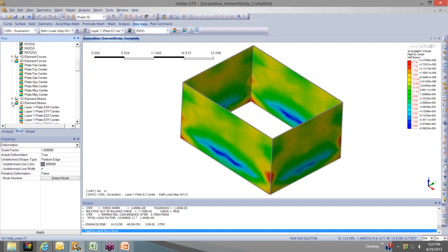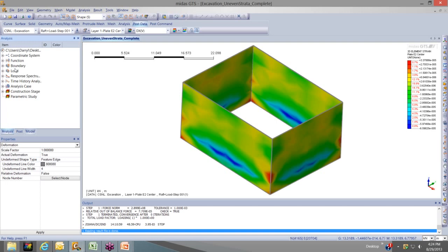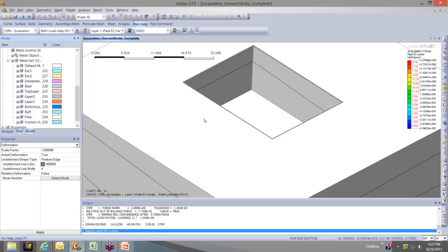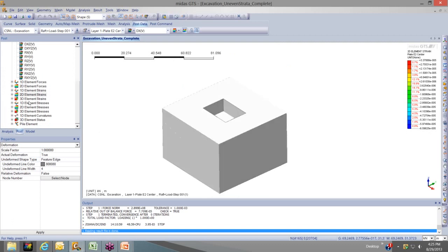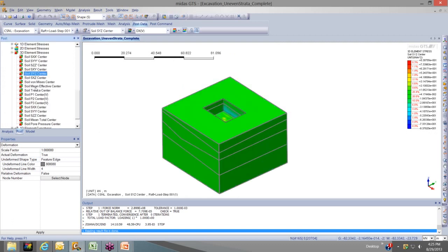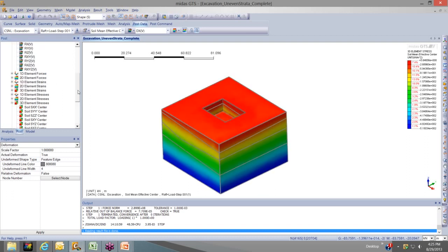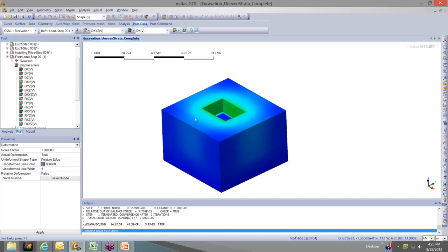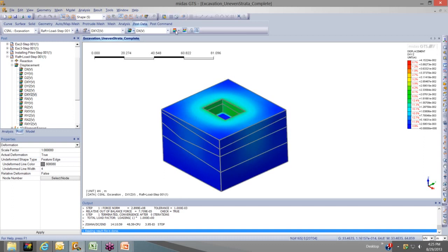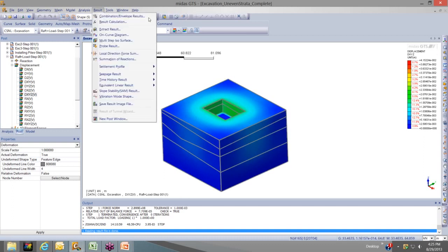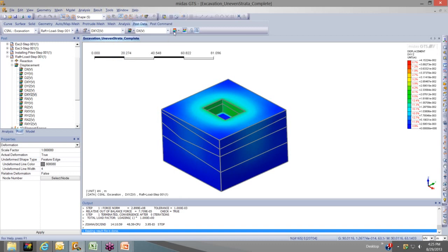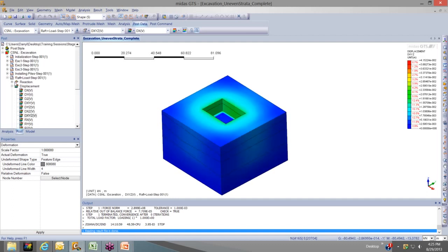So what else did I want to show you here? Okay, another thing. Let me turn on all the mesh sets now. Back to post. And then let's go back to some 3D options here. Okay, let's check the displacement in the X, Y, and Z. And let's say I want to see deformation. Okay, so let's see if I can show you the deformed shape.